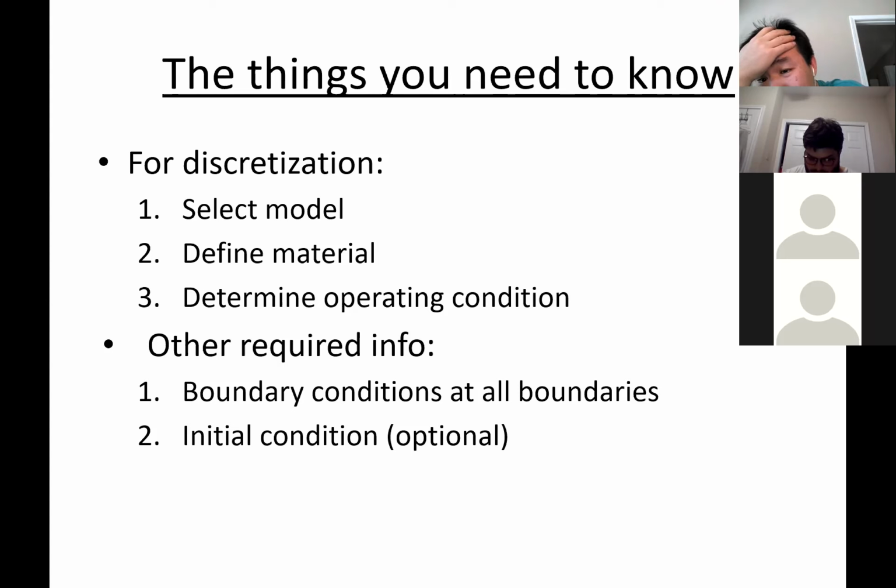No matter how pretty the picture Fluent gives you, it's garbage. That's why I always say Fluent is very difficult to use. It can be misleading to clients, because clients don't know. So you need quality control to make sure the result from your simulation is not garbage. You have to specify those conditions correctly.